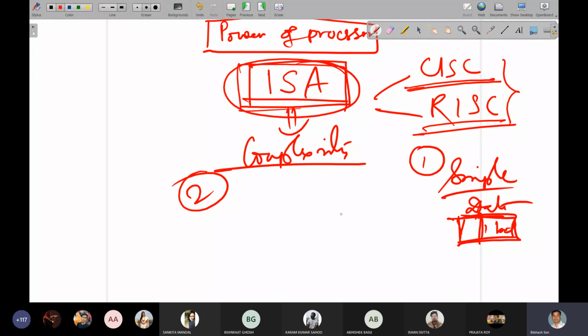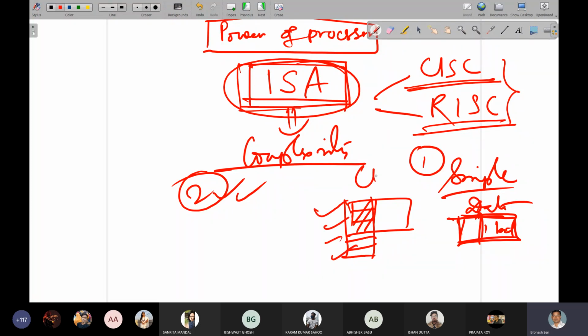If you have 3 instructions, the program memory should contain 3 locations to store the 3 instructions. So automatically the hardware requirement is influenced by this in the case of memory. Likewise, if the number of instructions is larger, then the control unit design is also influenced by this number, that means the control signals to be generated.